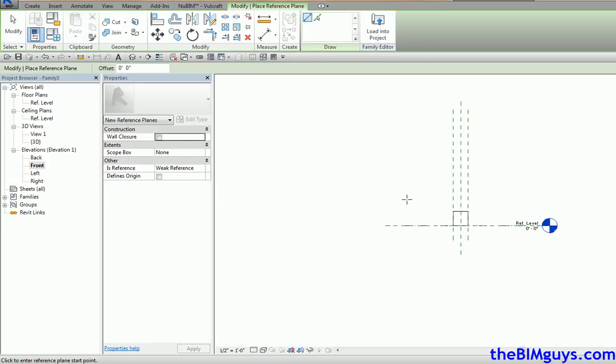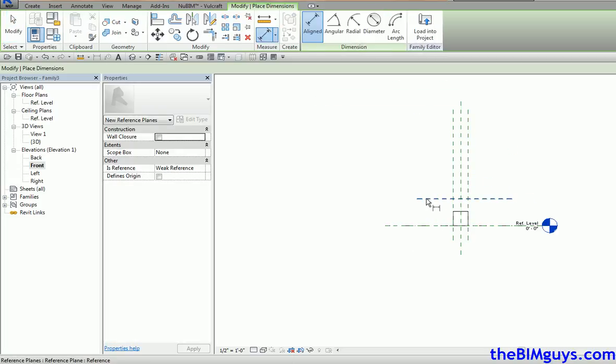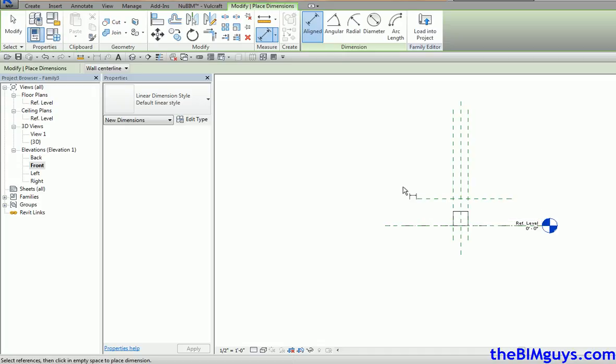I'm going to create a reference plane. I did that by create similar, and I'm just going to go down and dirty here. I'm going to put a dimension from here to here. Always use aligned. Here to here. Okay. Do not lock it to the solid. You lock it to the solid, it blows up. Always dimensions to the bones. Okay, those are the rules.